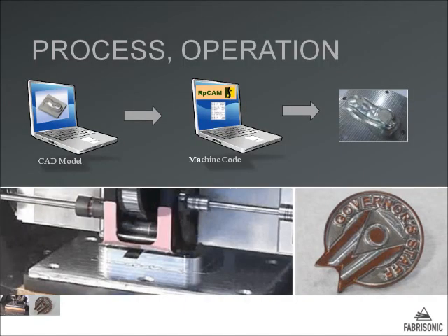All of the 3 UAM machines that we build are controlled using standard CNC controls called G-code. This allows us to use very standard industry products and to teach people how to use our products in a very short amount of time. If you have a CNC operator who knows how to run CNC mills, we can teach them to run our machine in just a couple of hours. In order to get from CAD to solid part, we have to create the G-code though for the CNC.